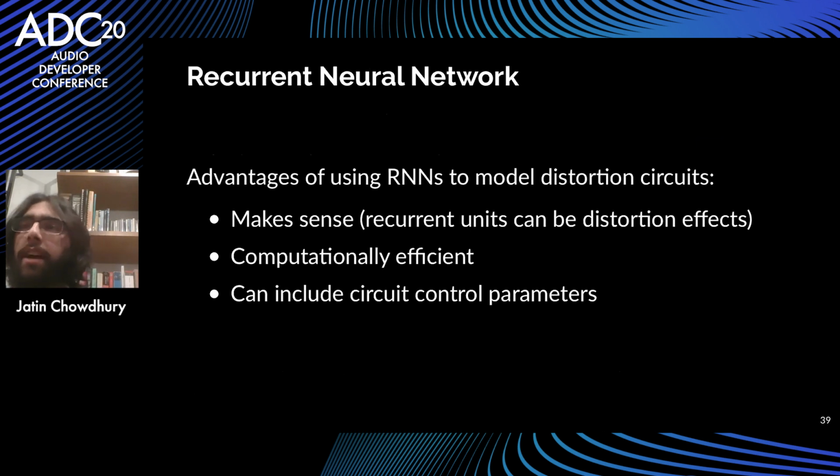So a couple of reasons why I ended up choosing this modeling framework for my circuit model. First of all, it just kind of makes sense to me. I often try to think about these things from a memory perspective, as far as what memory the neural network has. For the temporal convolutional network, the network is kind of like an FIR filter in that it only has memory of past input states. For the state transition network, it's a little bit more flexible. The system has whatever memory you give it through the state space equation.